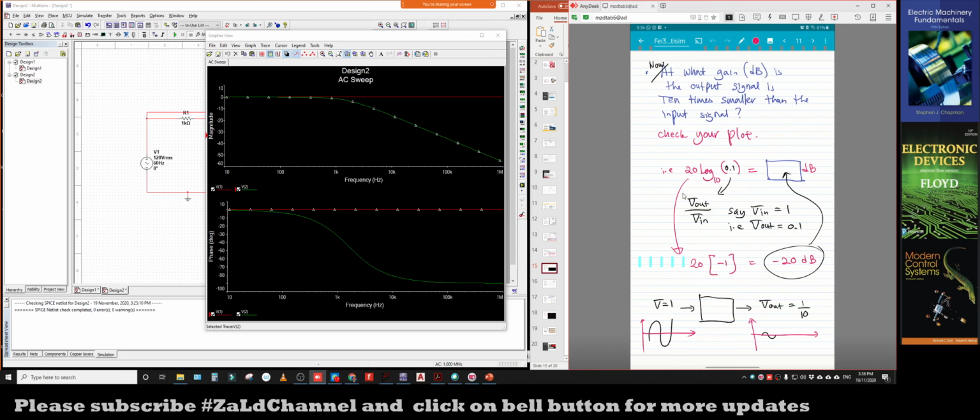Let's say we use this decibel equation here. We know that in this part it is supposed to be V out divided by V in. Let's say I put the input as 1, so 10 times smaller for the output is actually 0.1. So we have V out of 0.1 and V in as 1. We do the calculation based on this equation, so we get negative 20 decibel.